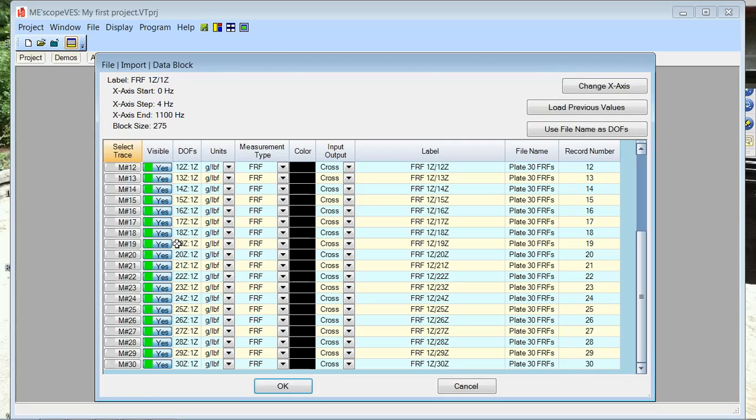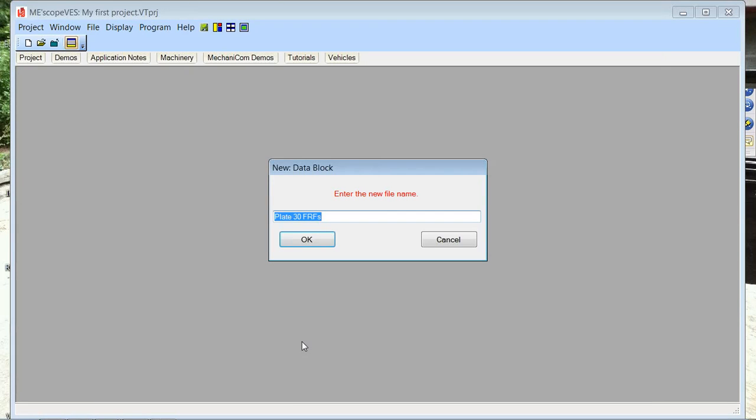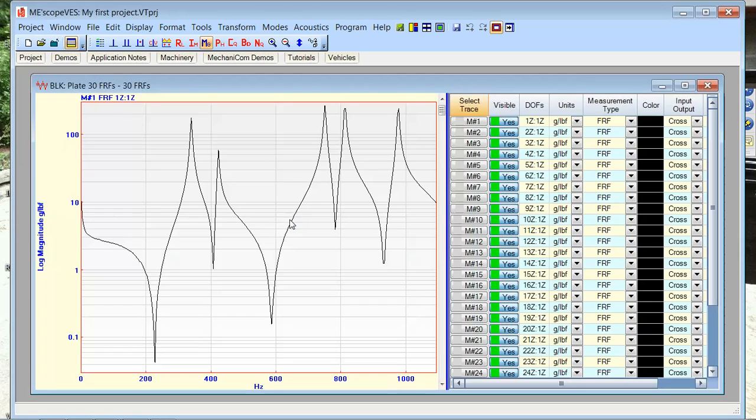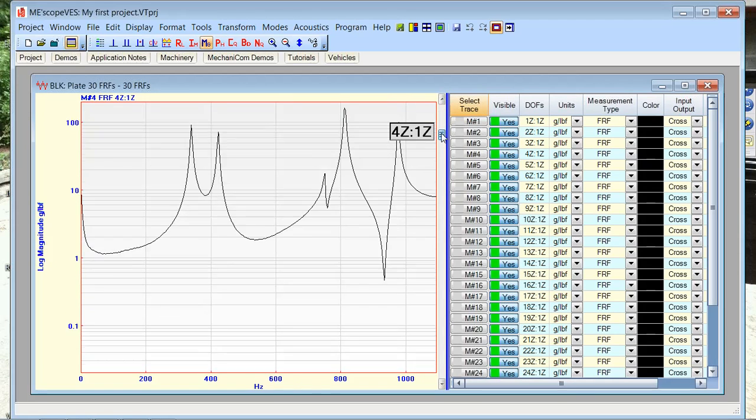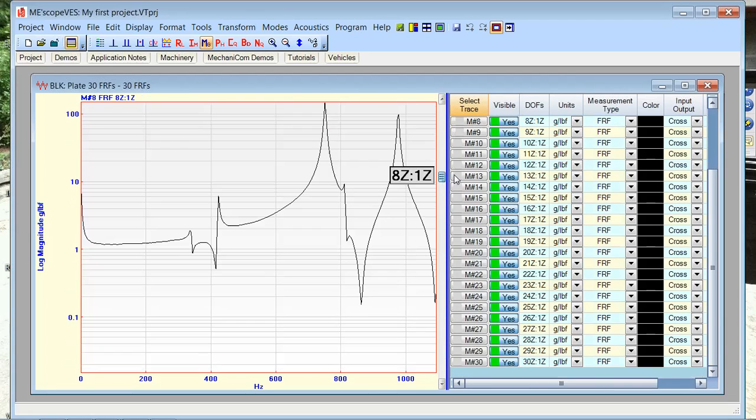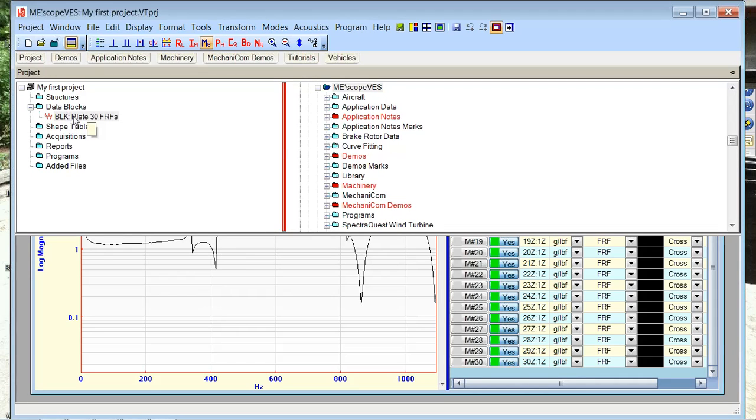Now, a substructure is merely a collection of points, lines, and surfaces. A triangle surface is between 3 points. A quad surface is between 4 points. A line is between 2 points. And then the very basic model that we would build has to have some points in it. So I've got to create some points in my drawing before I can add any of these other objects. But we're going to use a different tool that will create substructures for us that already have points, lines, and surfaces in them. So how do we do that?